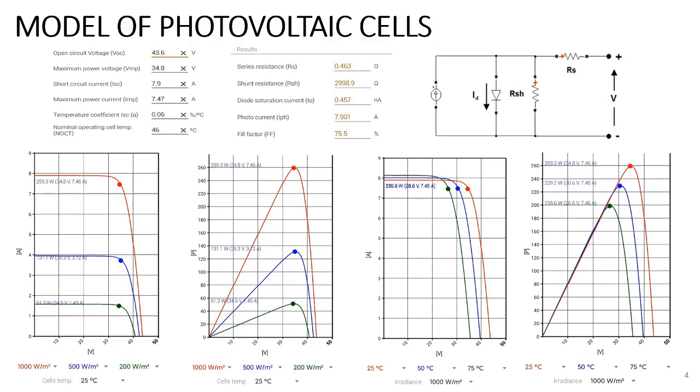This reveals that the PV output efficiency depends on its working temperature, and it is approximated by scientists that the efficiency reduction rate is about 0.4 to 0.45% per degree.